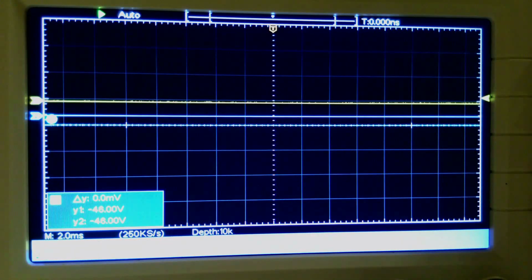The graph shows that the voltage rises and falls over time. Here we see the oscilloscope. The yellow line represents the voltage going into the total circuit. The blue line is the voltage across the resistor. The voltage across the resistor should be in phase with the current because resistive loads are always in phase. In other words, the current and the voltage are in phase with each other. So let's turn the circuit on.